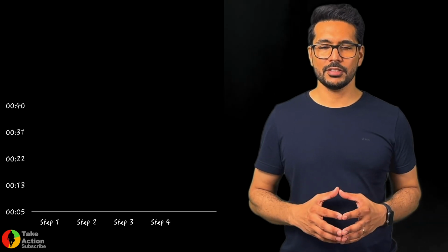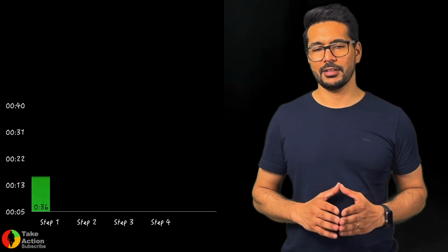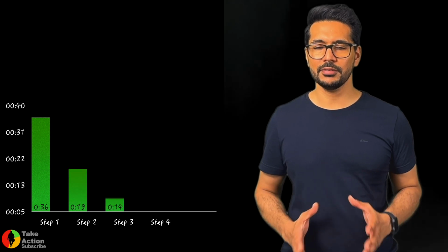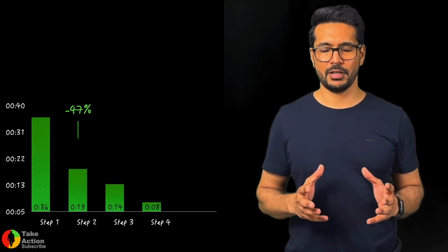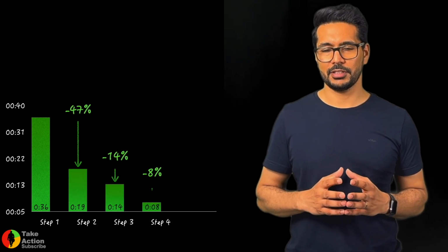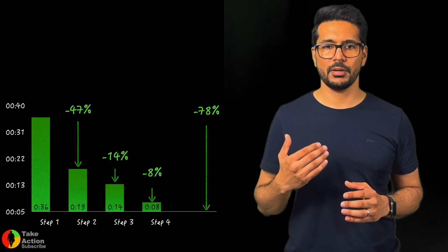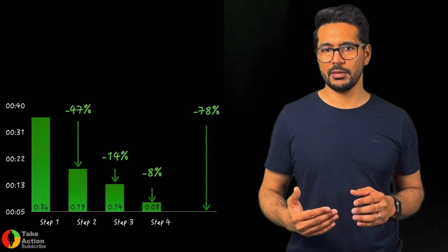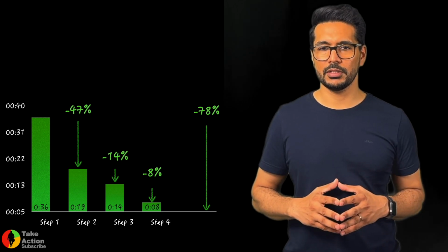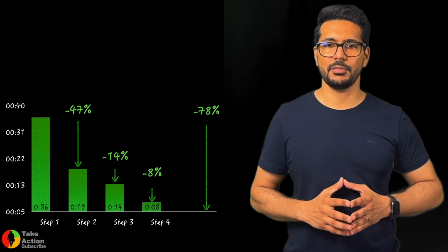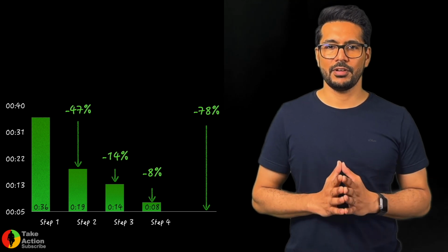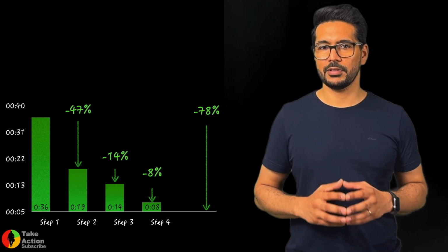So in the end, we can see the results. After applying this SMED method, we could reduce the total setup time by approximately 80%. And this was the first-time implementation. You can apply this method two or three times again after a few months, and you can really harness the benefit of this very effective yet simple lean tool.